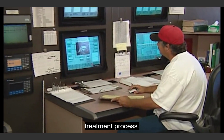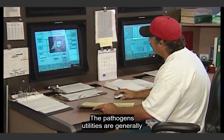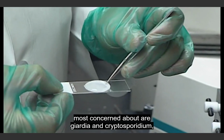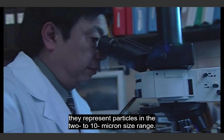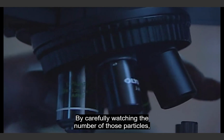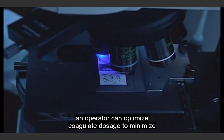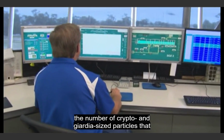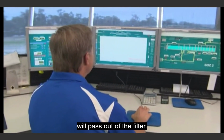Water professionals say the information particle counters provide can have a significant impact on the entire water treatment process. The pathogens utilities are generally most concerned about are Giardia and Cryptosporidium. They represent particles in the 2 to 10 micron size range. By carefully watching the number of those particles, an operator can optimize coagulant dosage to minimize the number of Crypto and Giardia-sized particles that will pass out of the filter.